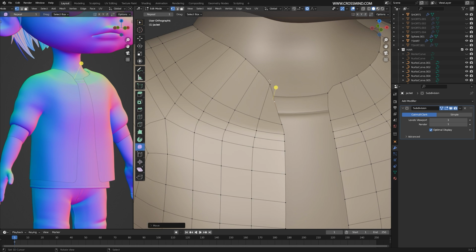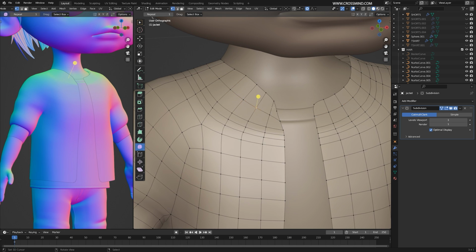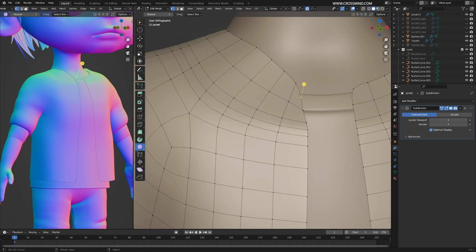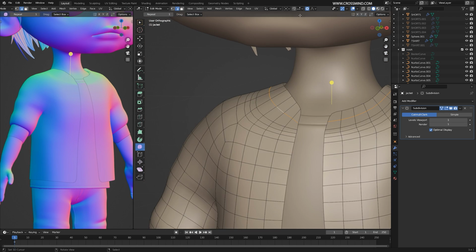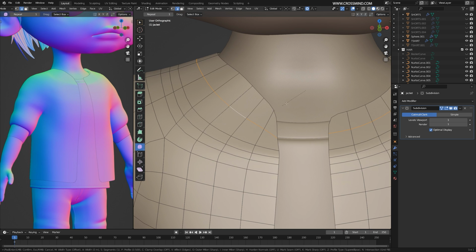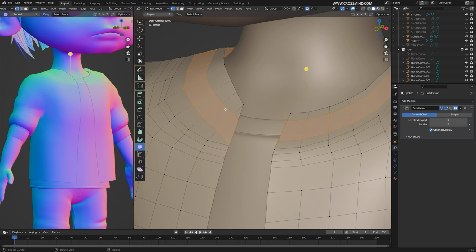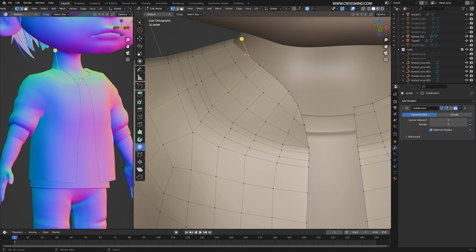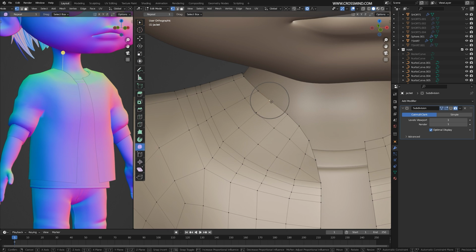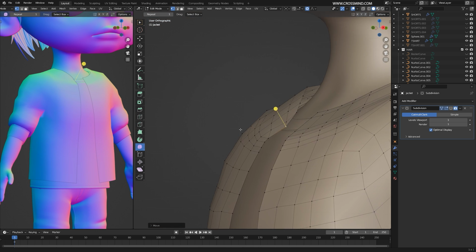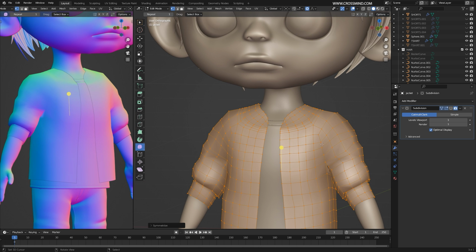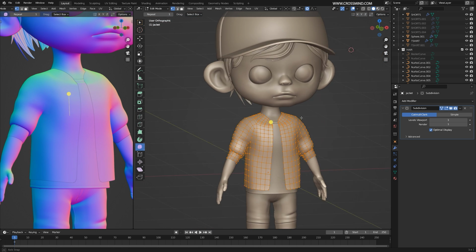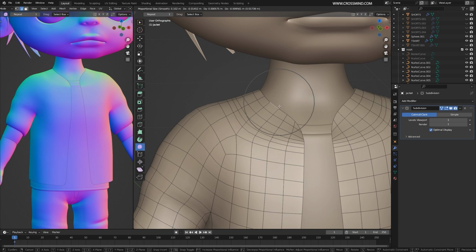And also going to add one edge loop in between. Control R to add a loop to fill this bigger stretch with few extra loops. Pretty simple standard standing rib knit collar type. I don't want to use loop tools because this is not exactly a round collar. And once we are done, let's symmetrize this. Let's see how this looks. So these are way too high on the neck. Instead, I can lower these down.